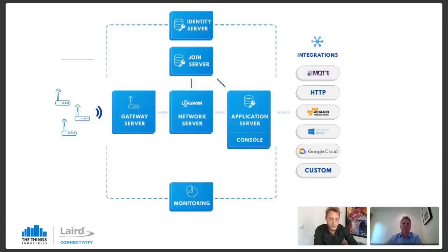We also gather statistics here about how many packets the gateway receives, and also about signal quality and channels, and also channel performance. The network server is really the implementation of the LoRaWAN specification. So that's really about decoding packets that devices send, identifying devices, processing commands that we send back and forth about which channels to use. So a lot of stuff that we abstract away from the application is in the network server.